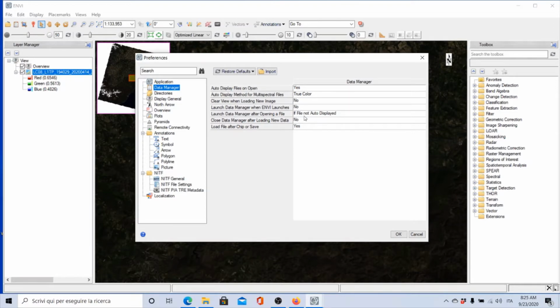And you see, we have other particular setups and so on. So, for example, if we don't want the true color, we can go to this field here, and you see we can change, for example, to CIR. That means it is a false color, where we associate to the red channel the near infrared band, for example. So you see, we can change the parameters here.